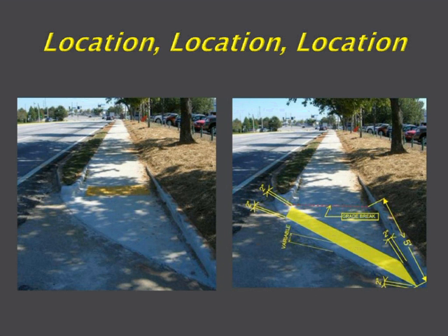And this is just another illustration of that. You'll see that on the left, they've moved the grade break back so that one edge is at the back curb and the other end is floating, which is fine, but the distance of that floating edge is more than 5 feet, so it should be moved to the back curb.